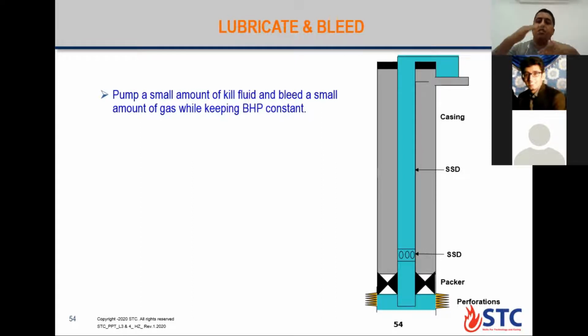After we repeat this sequence many times, it takes a long time and needs a competent crew and experience. There is a calculation, but the calculation is not in this course, it is not in the scope of this course. After that, I will replace all the gas from the tubing with kill fluid, so I will reach zero at the wellhead.